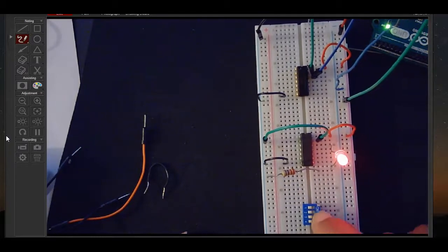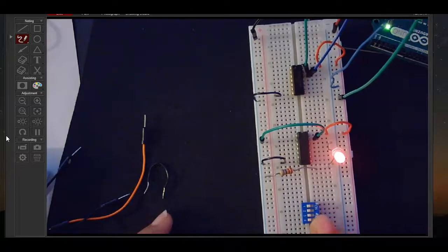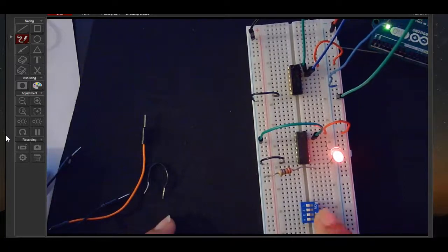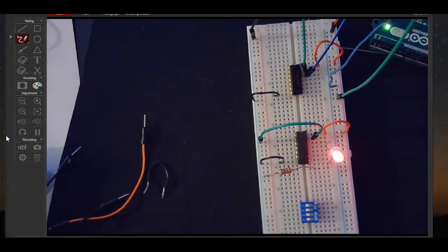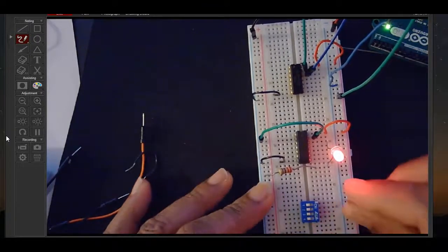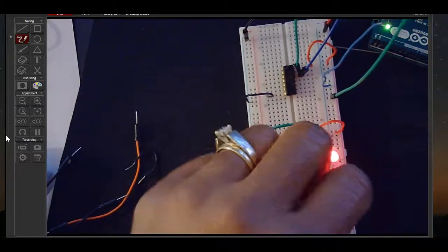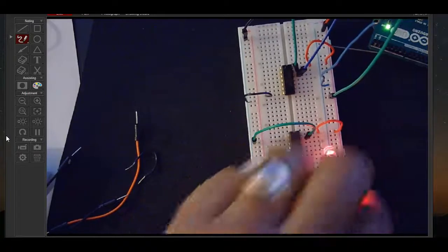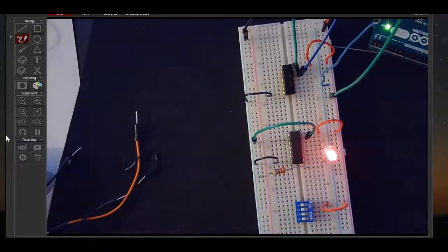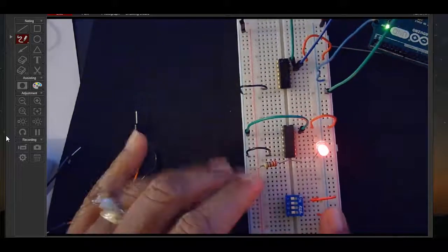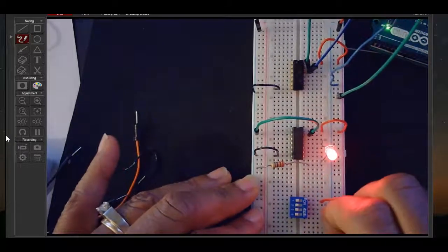First of all, on the side that says on, that has to be hooked up to 5 volts. We're going to use switch 1 and switch 4. So we're going to hook 1 up to 5 volts, and we're going to hook 4 up to 5 volts. Both of these.